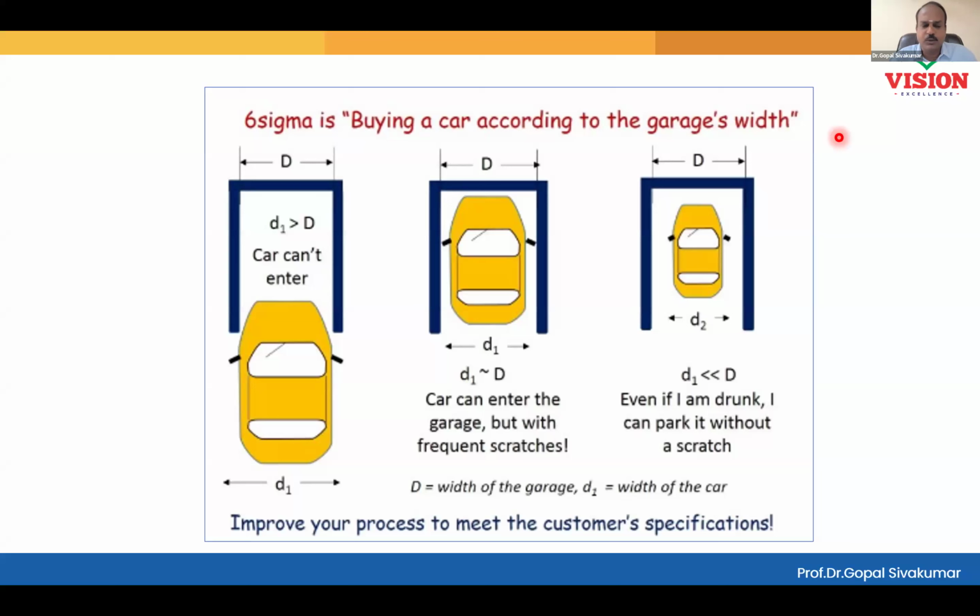So just capable scenario, Cpk equal to 1. If Cpk equal to 1, and the process is just capable, in terms of sigma level, the process is a 3 sigma process. So sigma level can be derived from Cpk. Am I correct? If Cpk equal to 1, what is the sigma level? 3. That means you multiply the Cpk value by 3, that will result in sigma level. Am I right? Cpk equal to 1, so sigma level equal to 3.